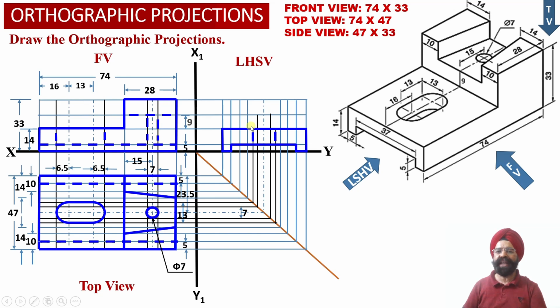So this is the apparent shape. Why is this apparent shape? Because over here it is a semicircular arc, over here it is also a semicircular arc, and we have got a rectangular projection corresponding to the semicircular elongated slot into the left hand side view projections over here.